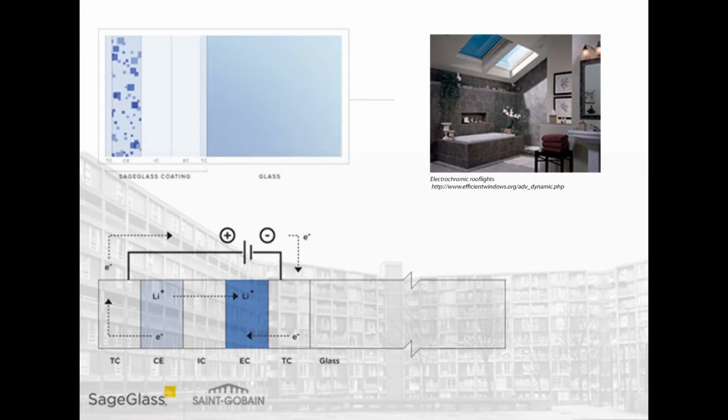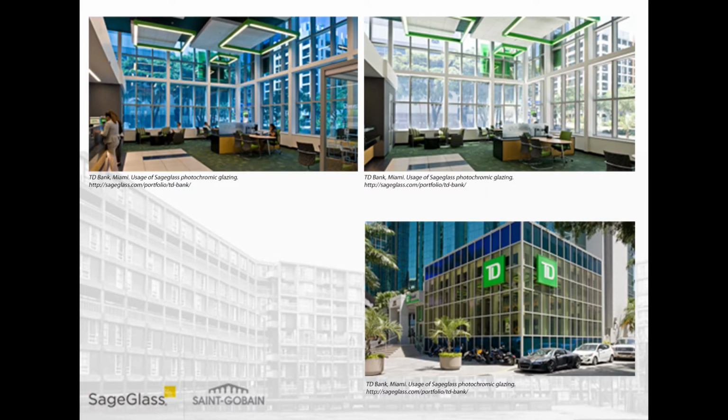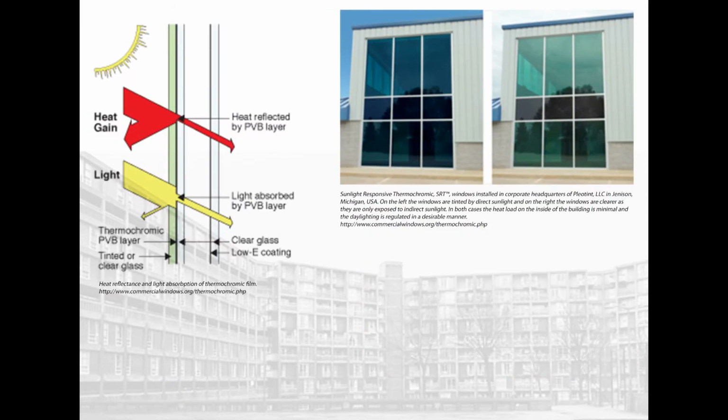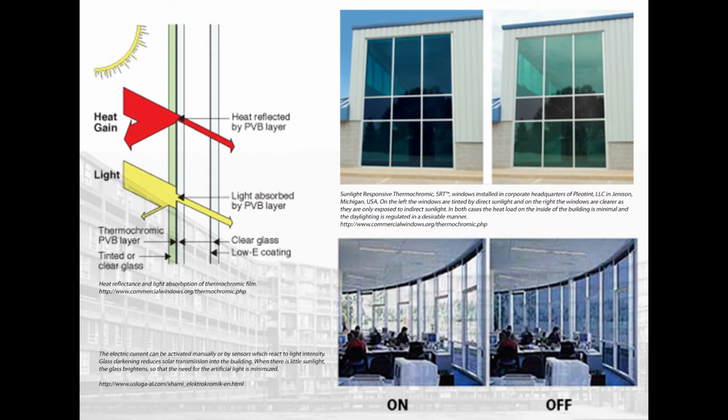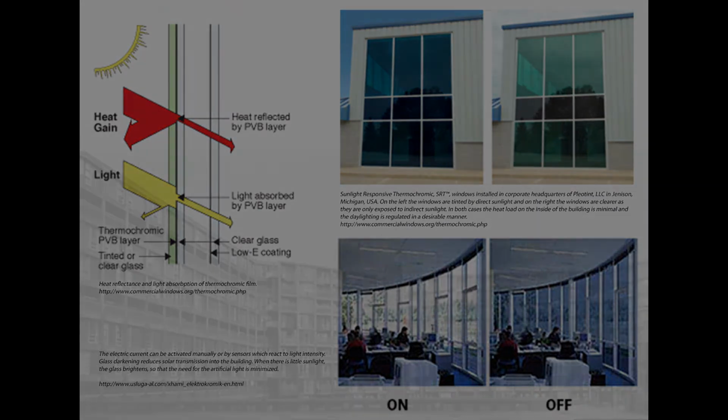Smart glazing controls glazing properties at different times of year. There are three main types of smart glazing. Firstly are electrochromic and liquid crystal glazing. This is where it becomes darker when an electric current is applied. Secondly is photochromic glass, which darkens in proportion to the degree of exposed sunlight. Thirdly is thermochromic glazing, which turns murky when it warms up, therefore preventing any solar penetration which causes further overheating. All in all, electrochromic glazing provides most user control and can be turned on and off.